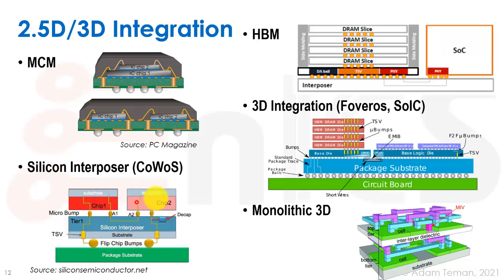And we have our different chips, which are going to be in whatever logic we want them, and we'll put them next to each other over here. And we put these through silicon vias. So we have a hole basically through the substrate that's going to be able to go down and connect underneath the chip. And then the interposer also has through silicon vias, but it'll also have routing between, as you can see here, between two of these bonds over here.